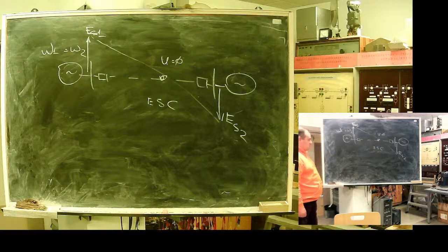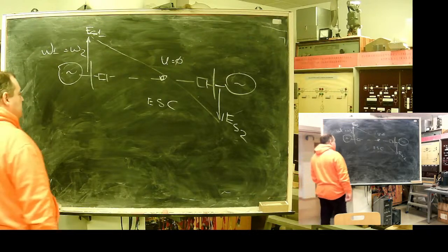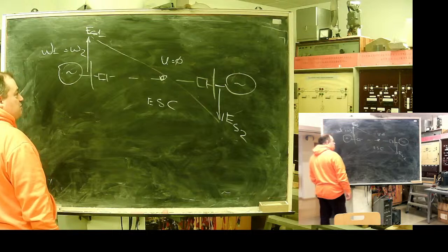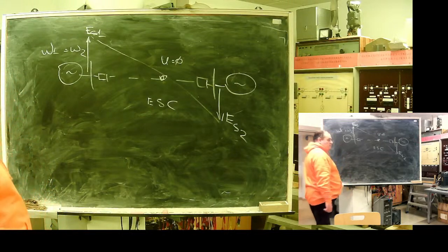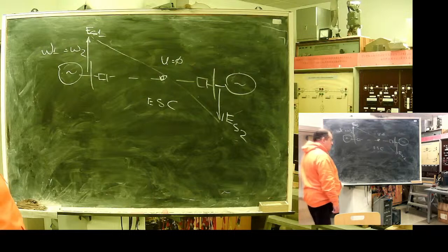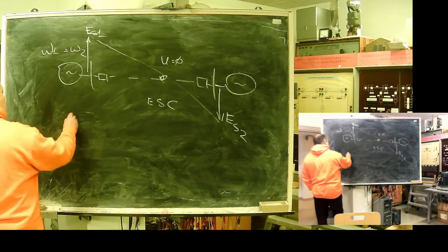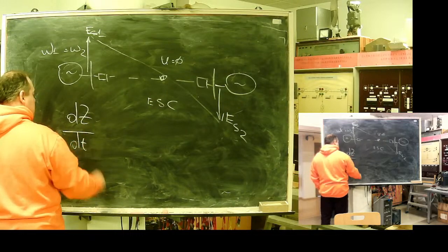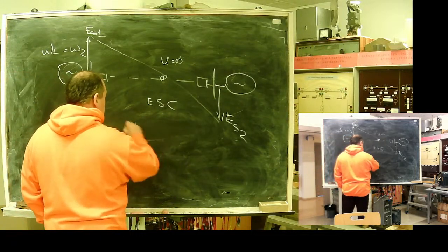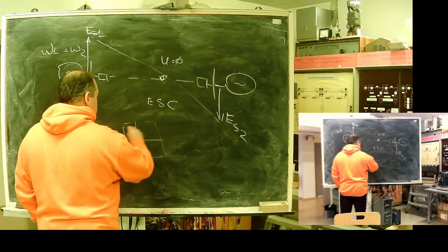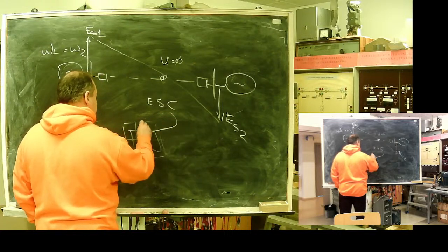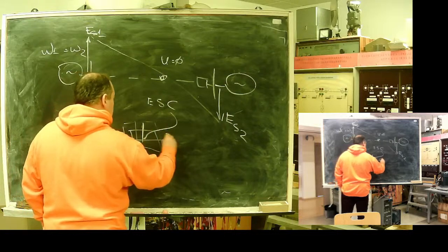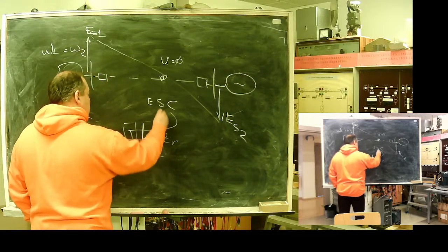To prevent this, the typical industry standard now is discrimination between a real line fault and an electromechanical transient by speed on which the observable impedance changes.